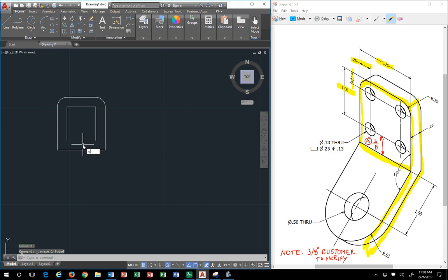I could leave it there and just offset it the 1/8 of an inch that I need to move it, because 1/4 plus 1/8 is 3/8. But you have to remember to do that. Otherwise, you will put it in the wrong spot. You don't want to do that. So be very, very careful of that. These lines become your center lines later, so don't be too eager to delete them. All right? Leave them in your drawing, because they become your center lines later. So I just drag them out.